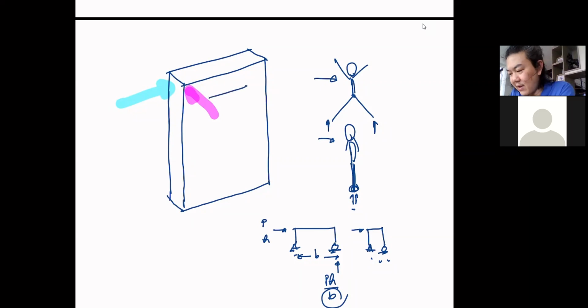So there's no way to solve this. So they create a hole here in the building so that the wind will go through here to ease off the pressure, right? And you know, the wind pressure is getting bigger and bigger the higher you go. So yes, they punch a hole through the building. It's not a small hole, it's a huge hole. It's like a few stories high.